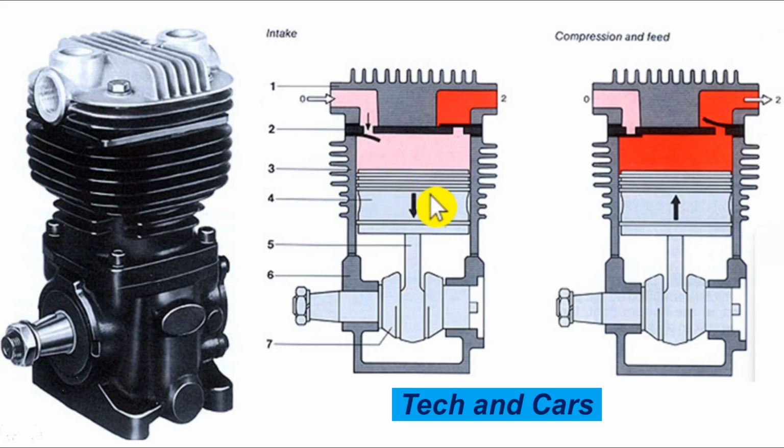Internal wear reduces the compressor's pumping efficiency. So this is often caused by lack of lubrication or prolonged service. And on some compressors, if the compressor has pumped enough air and the pneumatic system is filled, in order to reduce stress on the compressor and remove some load from the engine, some compressors have an unloader mechanism. That unloader mechanism, if it is faulty, if it is stuck partially open, then it constantly bleeds off air.